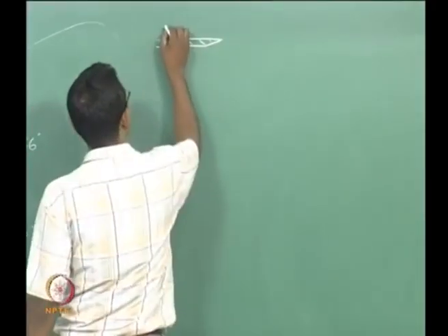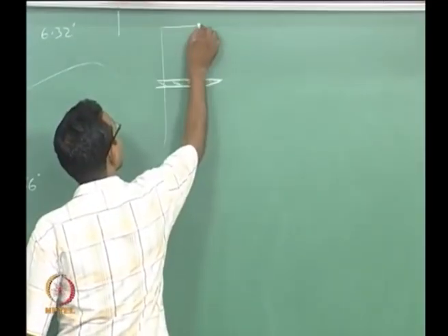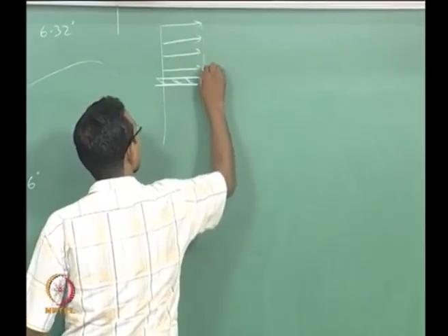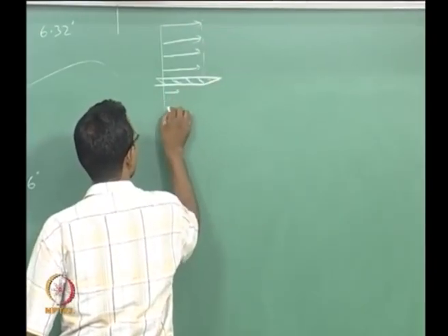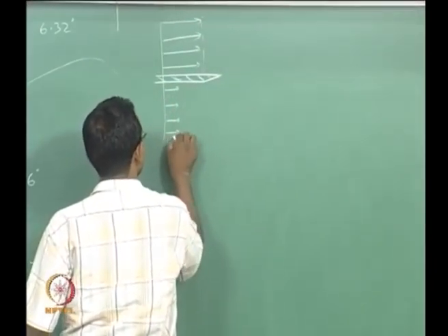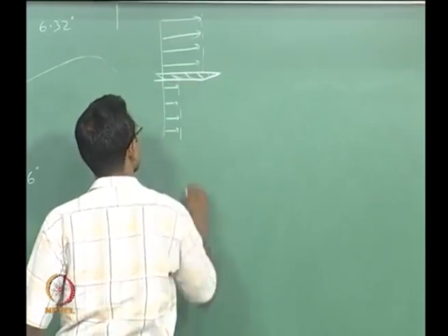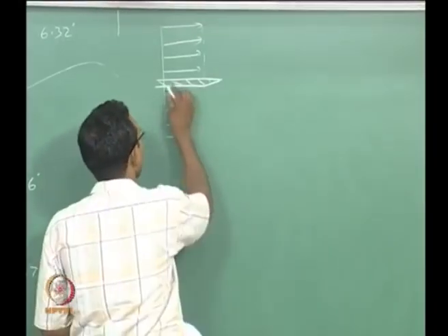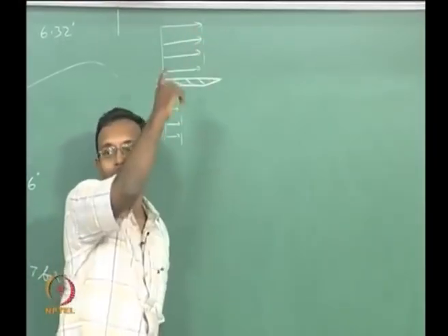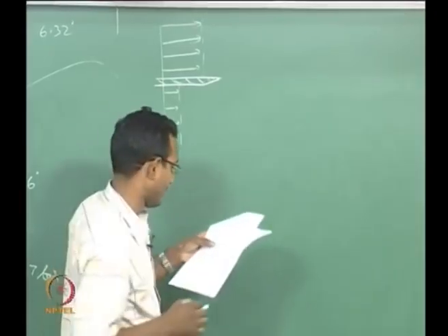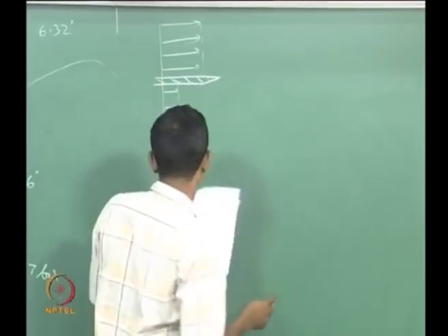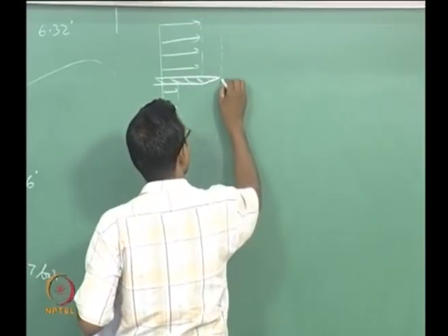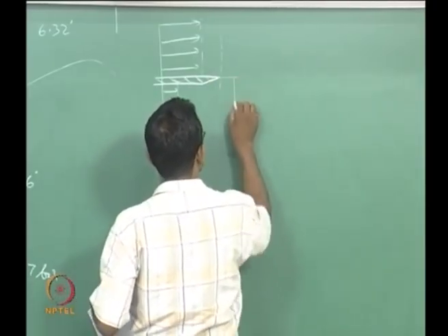If I have this velocity as something high, this is my velocity profile there, and this velocity being something low, these two fluid elements meet when they come out. I am assuming the plate is extremely thin compared to the dimensions I am interested in, so I do not need to worry about its thickness. When it comes out at this point, I am still going to have the same velocity profile.